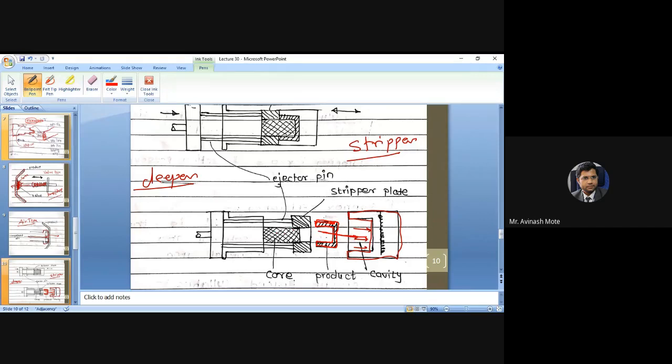So here is the stripper mechanism, this one, this core. This core is holding this stripper. This core is pushing. Look, from this side there is a pushing mechanism. This will push this core. This core will push this stripper, and the same way as the spring back mechanism, they will pull back the stripper when the component is stripped out of the mold cavity.